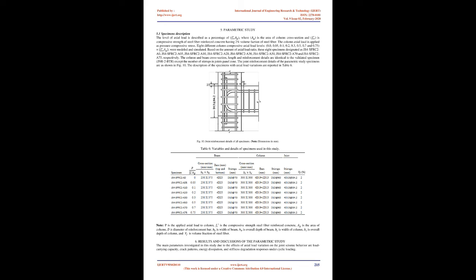In order to avoid the concentration of stresses on the concrete, premature failure or cracking at the cyclic loading point, 20 mm thick steel plates were used at this loading point. This loading steel plate is modeled with elastic properties, steel material having an elastic modulus, Es, of 200 GPa, Poisson's ratio of 0.3, and no yielding strength to avoid any premature failure in the steel plates.